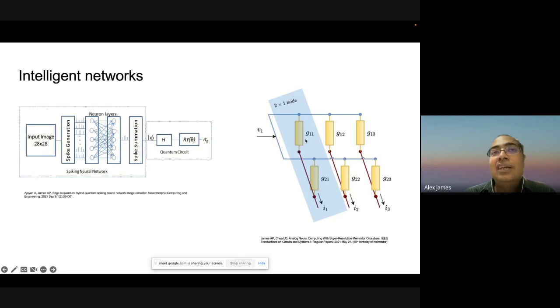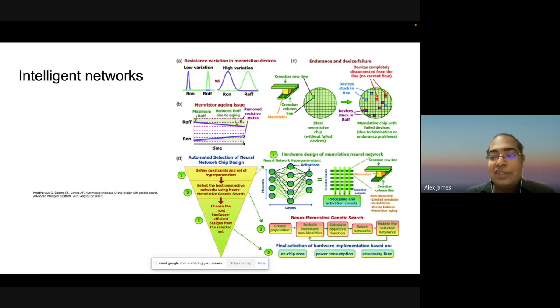For a start, getting around the math of it was a bit tricky. It was showing cyclical number patterns when you do that, especially if you take, for example, an 8 level memristor and put both of them together, one would see that eventually you can get more than 50,000 to 60,000 states out of it, which was interesting. And it could replace many of the systems which had trouble.